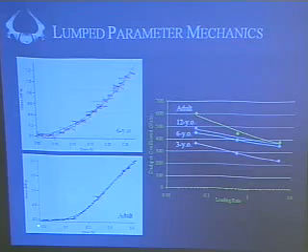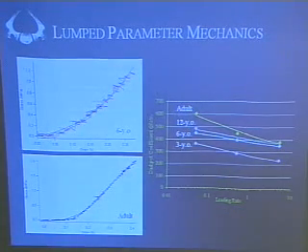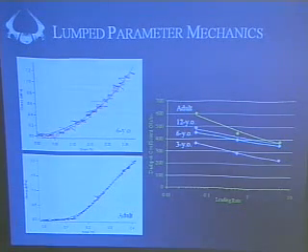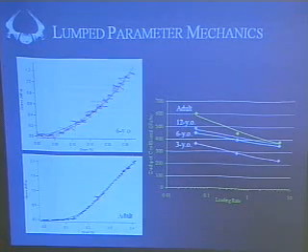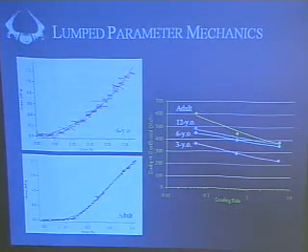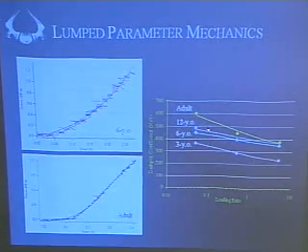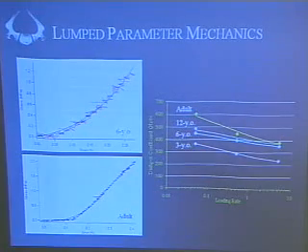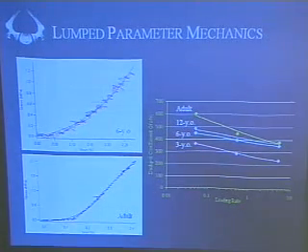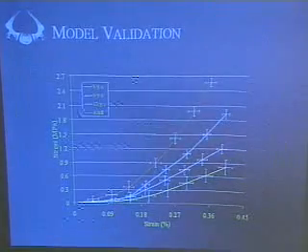For the adult, where we have a longer toe region and a steeper stiffness, it might miss a little bit down here, but I still think we have a really good approximation of the exponential fit to our experimental data. When calculating the hysteresis energy and the dashpot coefficients, we see really nice increases in the dashpot coefficient with maturation, as well as a decrease with loading rate, and that was all expected.